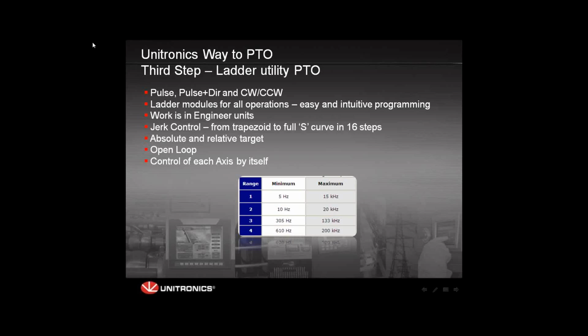If, let's say, you tell the motor to move 100 steps, there is no feedback. You don't know if it really did the 100 steps. You can only tell it what to do, but you don't get any feedback back. So in order to perform closed loop functionality, what you need to do is to use external devices. But the PTO itself does not do that.